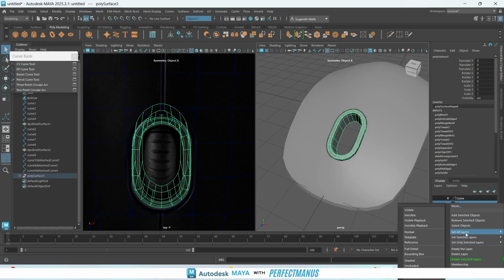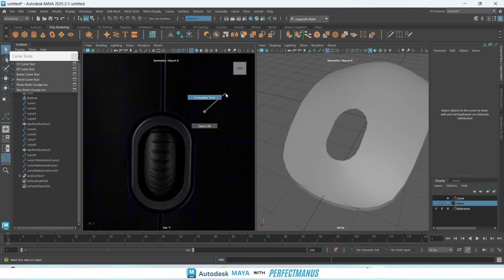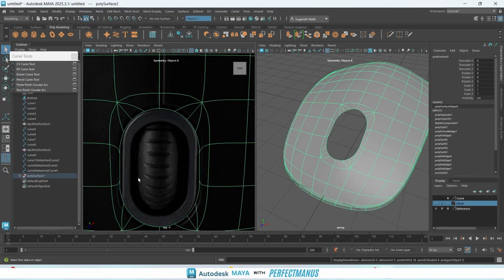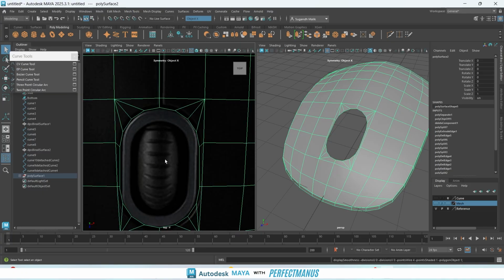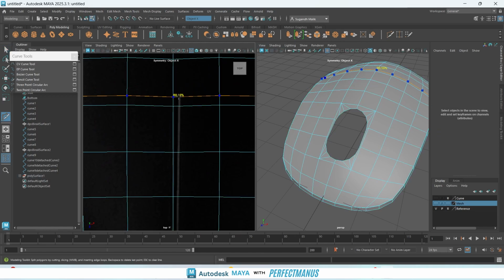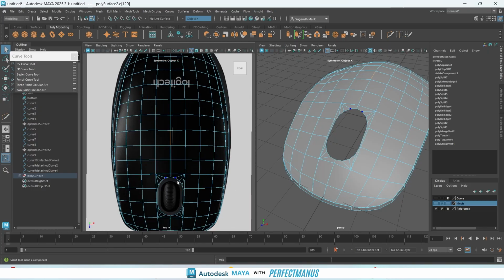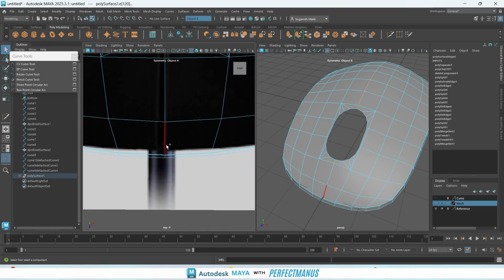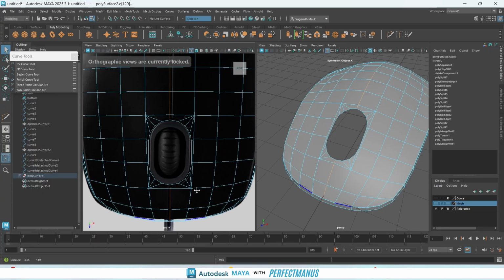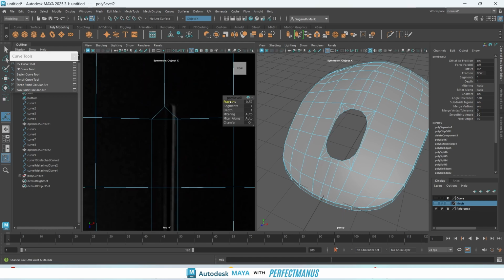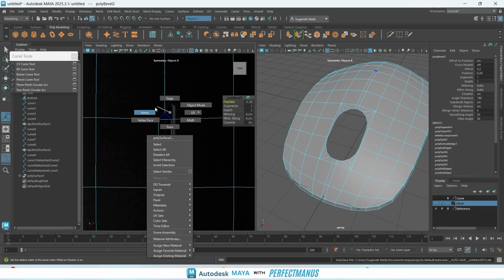We select the mesh, we send it there, and for this part, when we smoothen it, you can see that a circle is probably created. You have to create this cut. So for this one, either we can put a loop cut here, or this will be automatically created when we create something for this one. So simply select this one, and for this one. Now when you bevel it, you can see that there is a difference there. You can decrease its fraction, you can increase its points.